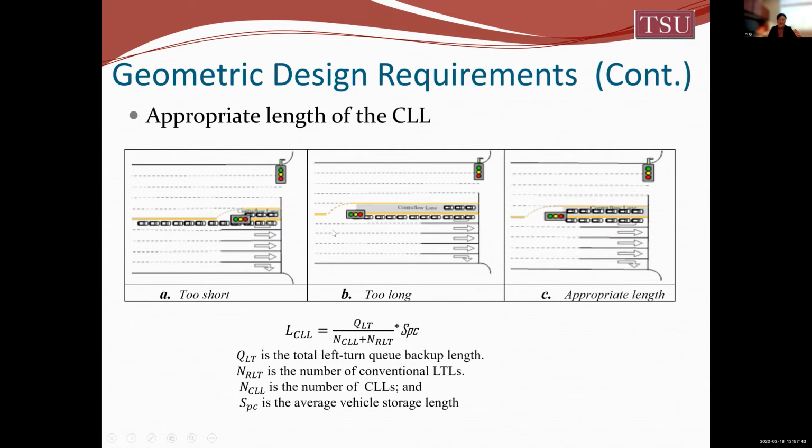If the control flow left lane is very long, you have to put the pre-signal very far from the main intersection. The problem is the pre-signal lights only turn green for a very short time period. Most of the time when vehicles arrive, they will see the pre-signal lights are red. So all these left-turn vehicles have to line up in the regular left-hand lane.